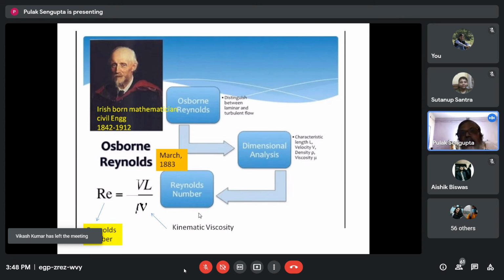And that's why in many geological situations and in mechanical engineering, where you have oil in cars and in many other places, people are more interested in the flow properties, not in the fluid moving at a constant speed. So sometimes you need a material which for a given pressure moves faster, and some other materials move slower. Depending on your need, you will choose the material. So they use this kinematic viscosity.